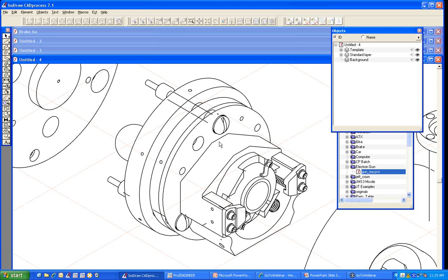Also, things that are important in IsoDraw, this is an ellipse right here. Now, if it were coming out of the CAD system and you were doing cleanup on another tool, this ellipse might be anywhere from 10 to 30 line segments, and each one has 2 control points on it. Those can add up to a significant file size. IsoDraw actually sees this as one element, an ellipse.